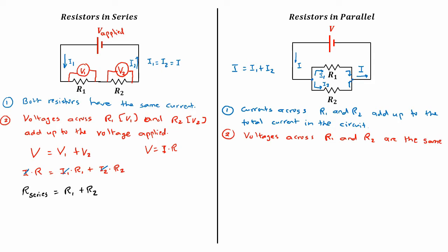This is a bit tricky, but if I place my voltmeter here and try to measure voltage 1, then the two probes of the voltmeter, if I place them here or along this line or at the junction, again, here or along this line or this junction here, it doesn't matter. Within the line, there is no voltage drop. So it is as good as saying that I can place my voltage probes at the junctions, correct?